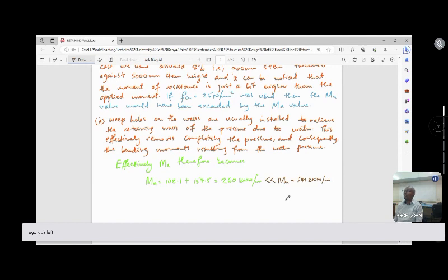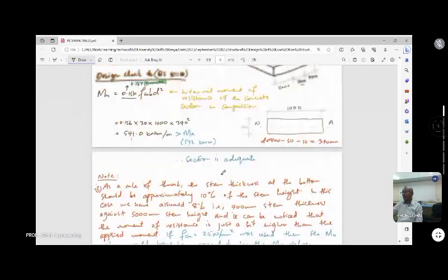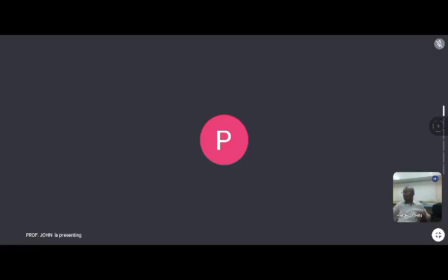If they block, what happens? The pressure grows. We move from 260 back to 522. And then if we had designed for only 260, of course the wall will fail because the weep holes are no longer providing relief to the wall.